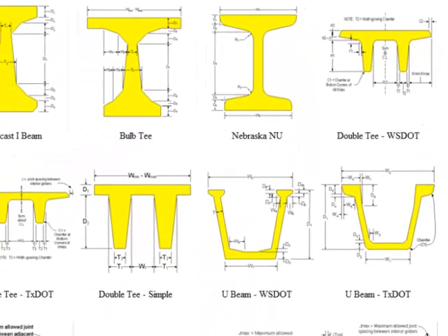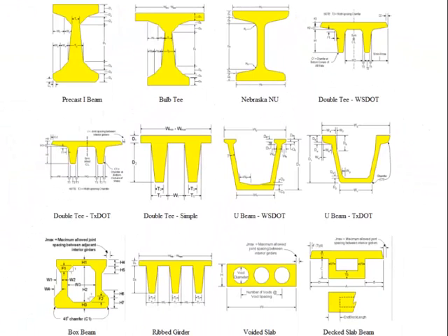Of course, PGSuper is a pre-stressed girder design program, so getting the girder data correct is really key to success with the program. If a girder entry is poorly defined, it can result in bad computations and cause PGSuper's design automation algorithm to fail, or at the very least come up with suboptimal designs. So you really need to plan out and use your engineering judgment and not a small amount of testing when you create a girder library entry.